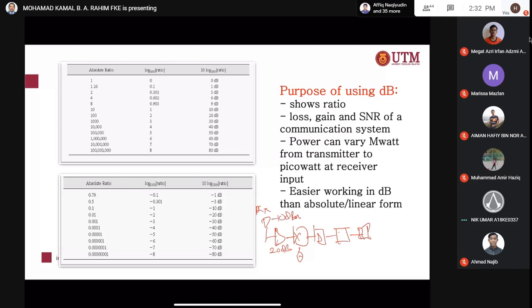I will show you the dBm later. Then losses, we have minus 6, we amplify another 20, we have a detector at minus 5. What is the output here? The output is equal to minus 10 plus 20 minus 6 plus 20 minus 5. So you can see it's very easy to do the calculation from the receiving part up to the output part.